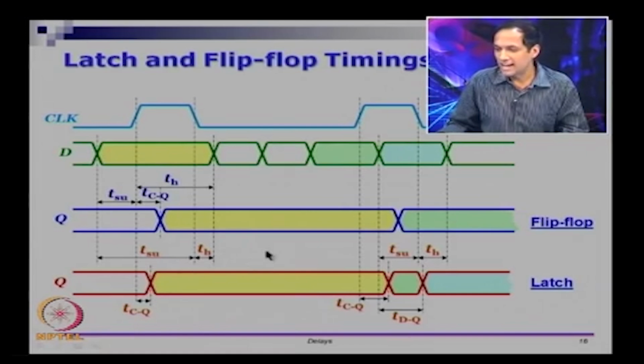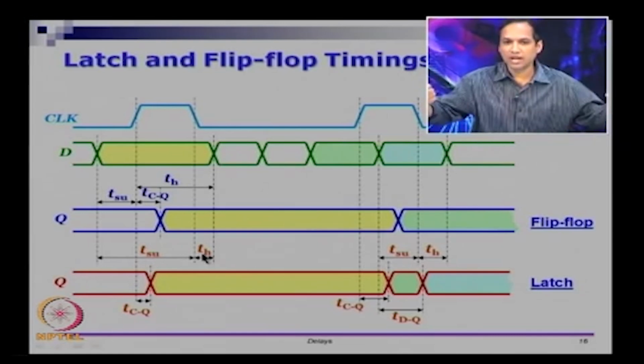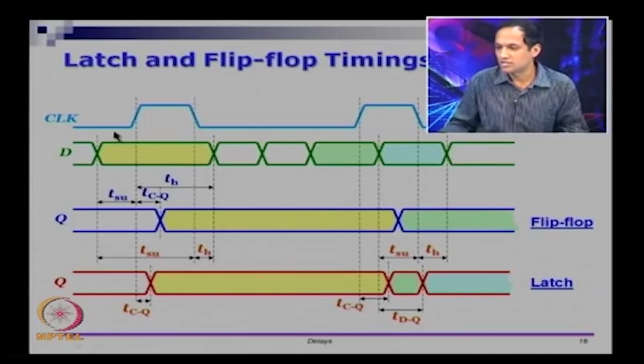If you go and look at a latch, the setup time is measured from, again we have the closing edge which is coming here. With respect to here, you see how long should the input be kept constant, that is called the setup time. Once the closing edge comes, how long it should be kept constant, that is the hold time, and the setup plus hold time is a continuous window of time in which the input should be kept constant. So, it is kept constant during that time, and after the pulse has arrived, right.